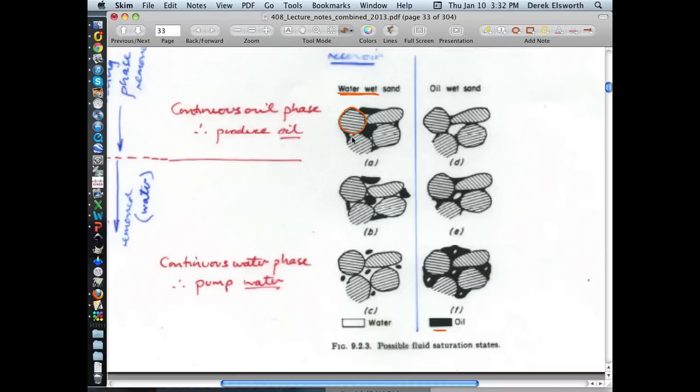and there'd be no gas in this. If you pump water into here, which is how you get oil out, you don't just suck oil out, you have to replace it with something. So you suck the oil out and replace it with water, and you change the saturations to maybe 50% oil and 50% water. You change the topology, if you like, the connectedness in this pore space. And as you further pull out oil and put in water to replace it, you end up going from this,